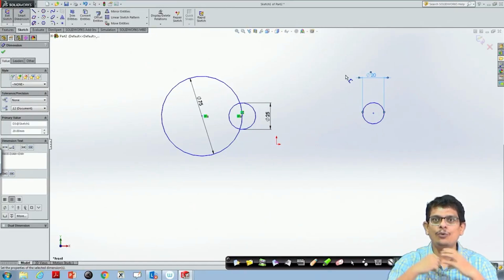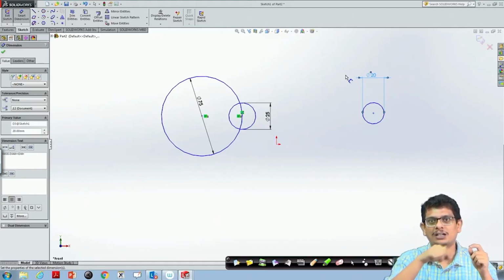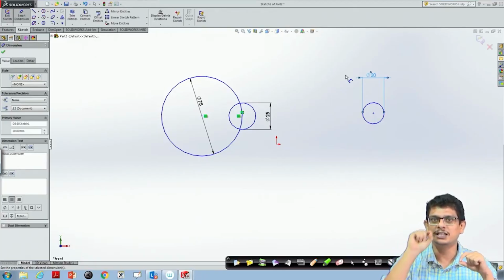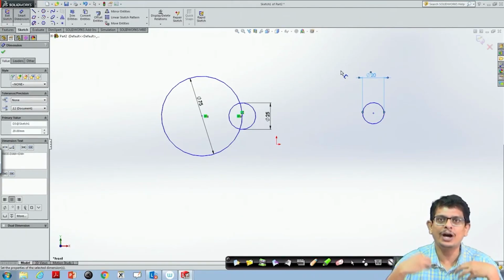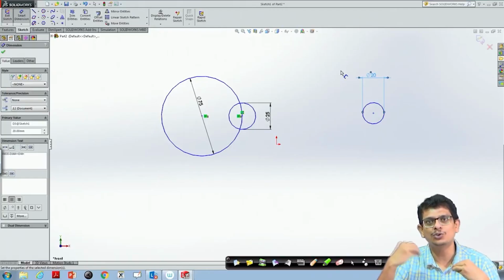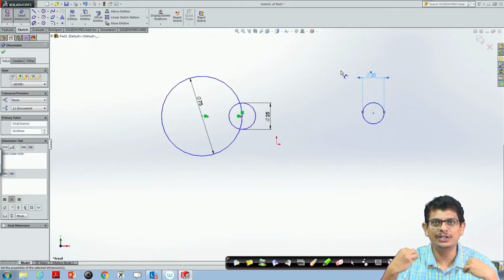Do you remember how we constructed that 3-point circle at the manual level? From those points we draw the arc, construct bisectors and draw normals, and where these normals intersect, we locate the center. That is geometric representation, but at the mathematical level it works in a different way. So, whenever you are using a software, you always go back and check how a geometrical construction by hand drawing was done and how this software really works.